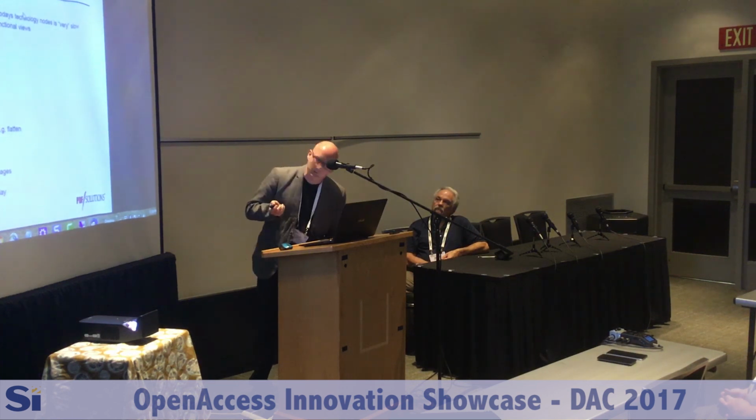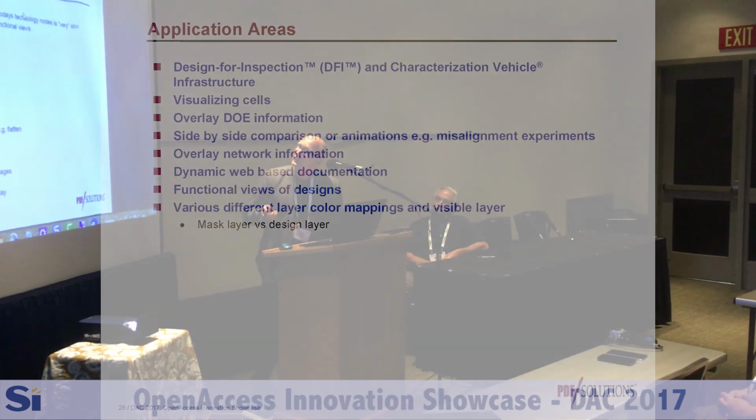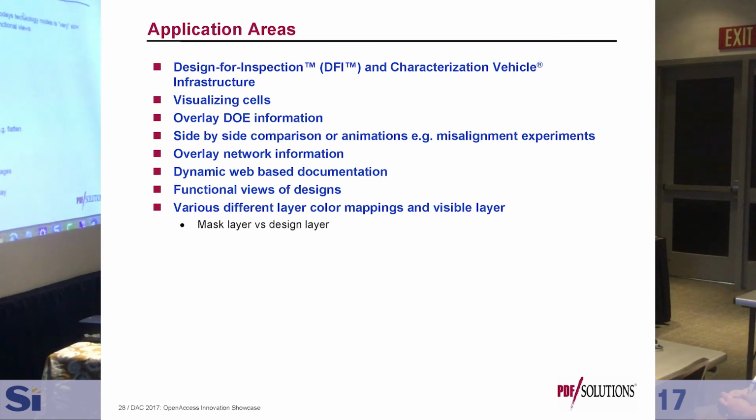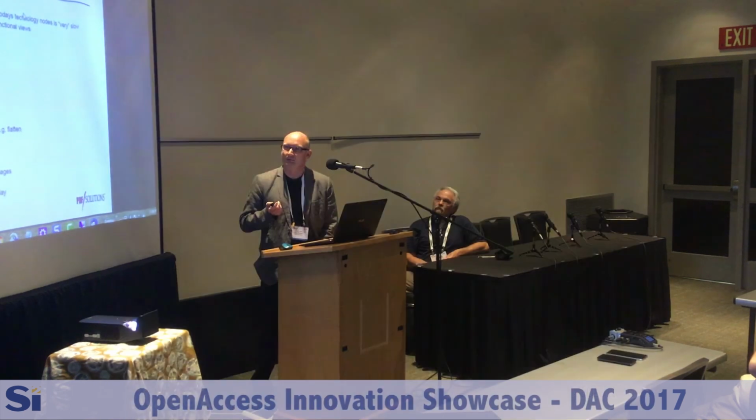We also may be thinking about, let me see, this comes later, sorry. You overlay useful information. As I mentioned, we want to maybe overlay simulated layouts. So how do they really come out when they are printed on the mask? Or we want to extract some attributes, which we want to overlay, like critical areas or other interesting things, network information. Even 3D views would be really helpful, or cross sections, because sometimes from polygon data, understanding the function of something is really hard without additional aids.